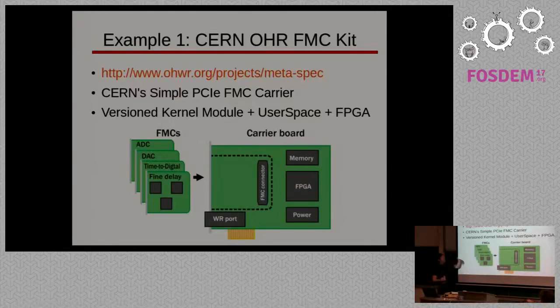So by using hdlmake, we have generated different Linux packages for each of these different modules that not only include the kernel module, but we have also packaged the user space program and also the FPGA, so that if we want to make a Linux runtime in which one of these modules needs to be supported, by just installing one of the packages, all of the different ones are generated and installed.